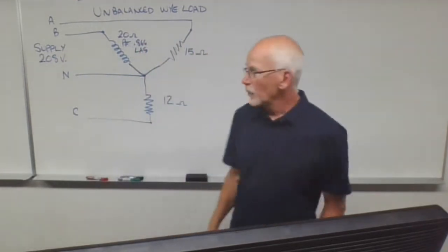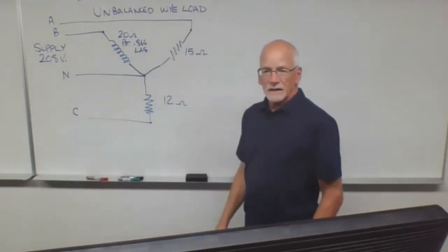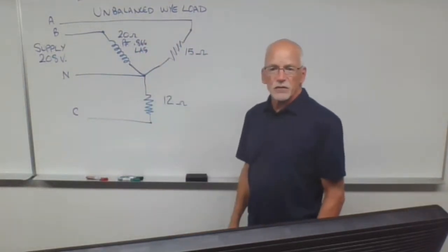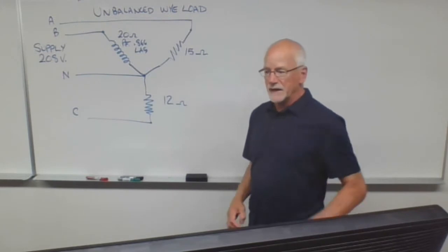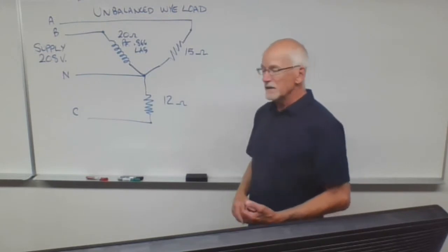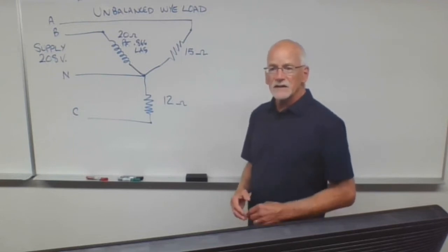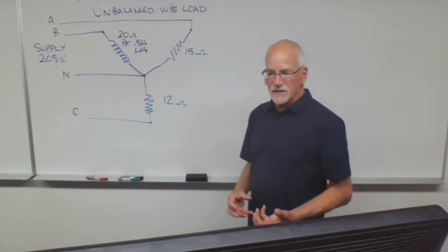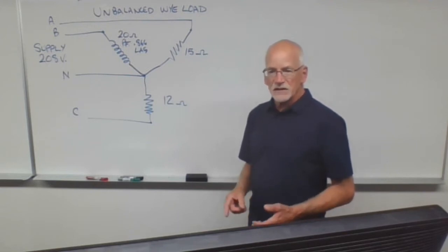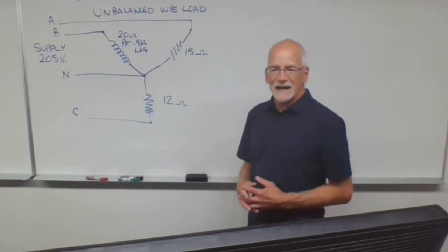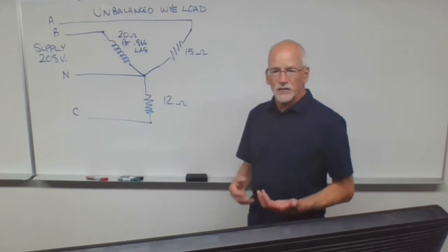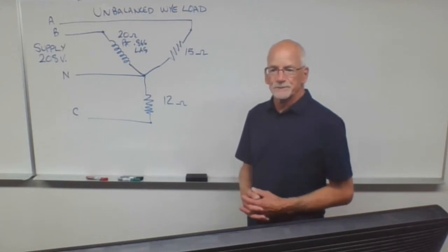From what you have here, pause this recording and find out what the phase currents are for this load, for each phase A to N, phase B, phase C to N, and draw a phasor diagram showing the relationship between the phase currents and the phase voltages. Actually, do a drawing that shows all three phase voltages and all three phase currents for this load.